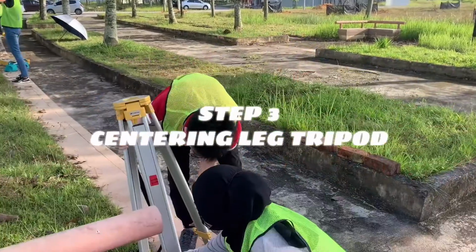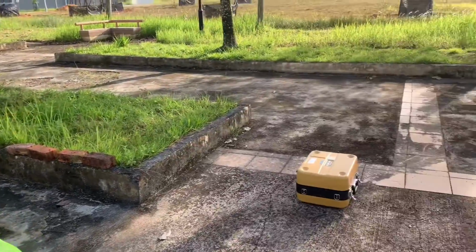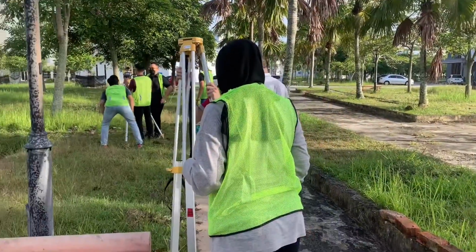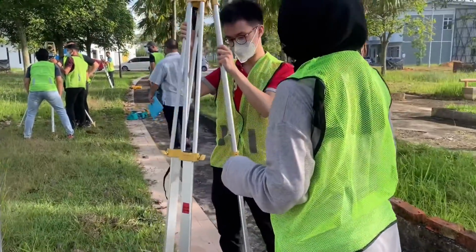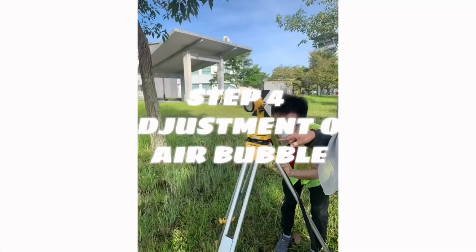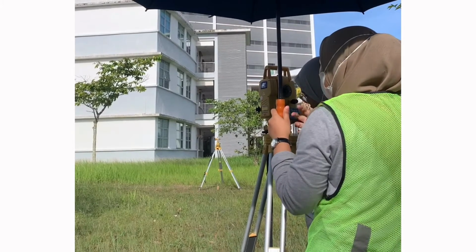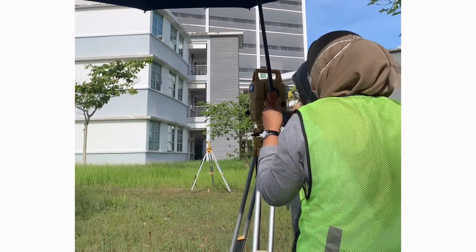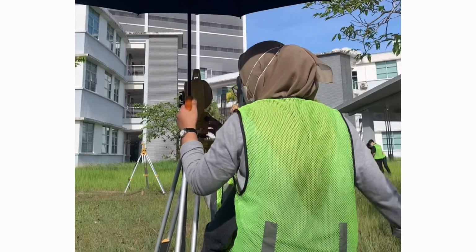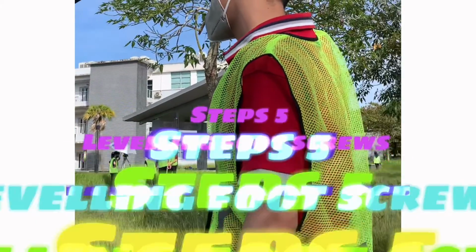Step 3. Centering the tripod. Centering is carried out by loosening the screw, tightening the tripod, and moving the tripod until the point appears just above the mark of the eyepiece plummet. Step 4. Adjustment of air bubble. Perform adjustment of the air bubble. This adjustment is supposed to place the air bubble in the center of the tube in any direction shown through the binoculars.